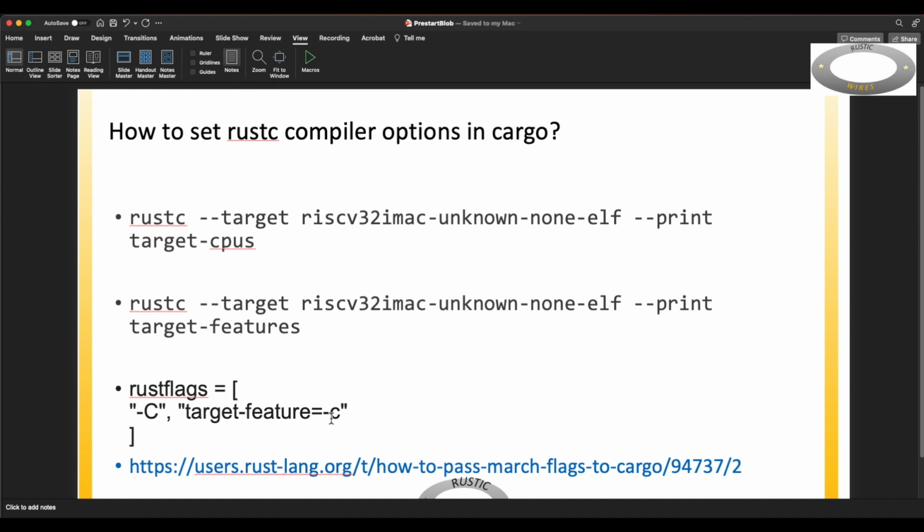What I mean by that is, when you enable the support for compressed instructions, then a few instructions would be 16 bits wide and a few would be 32 bits wide, and that would cause misalignment in address, because instructions can be 4 bytes or 2 bytes. Then of course any address can be 2-byte aligned instead of 4-byte aligned, and at this stage I do not want that to happen. That's why I have prevented the compiler from generating those compressed instructions.